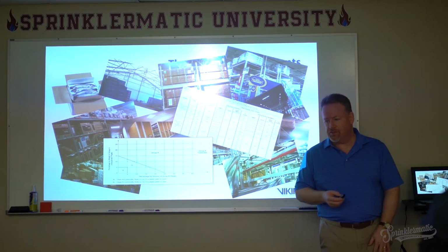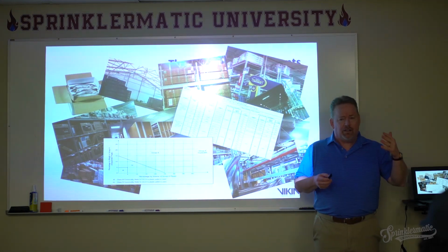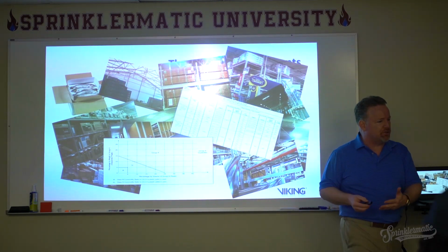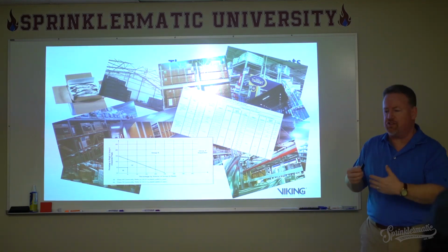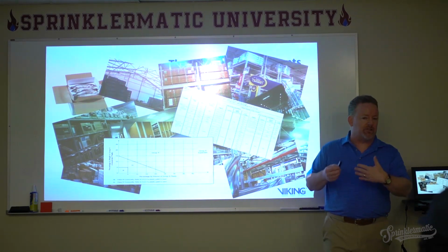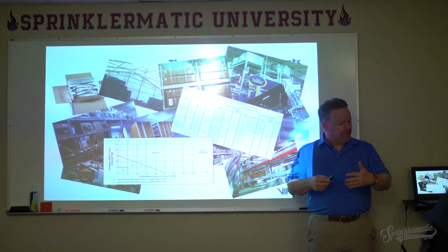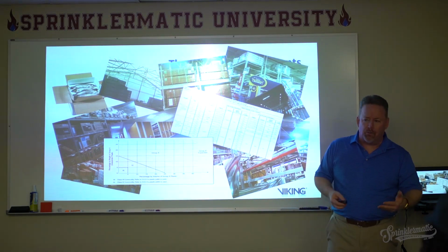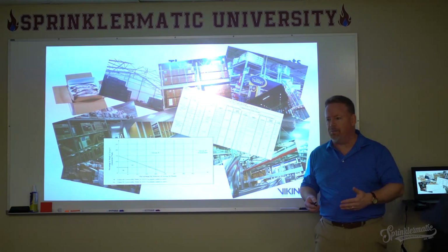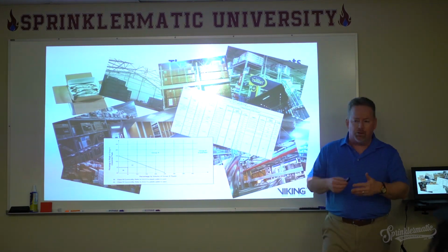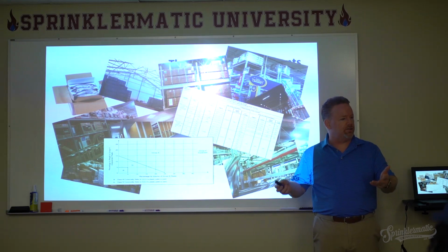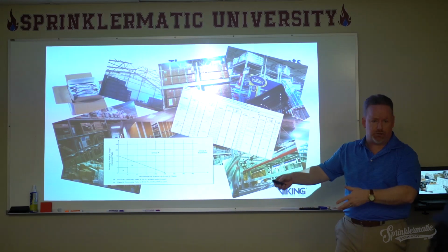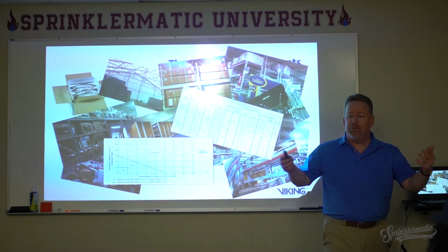Because when it comes right down to it, NFPA 13, as far as the design is concerned, has a series of different chapters that deal with the protection of storage, that deal with different ways that sprinkler systems are designed to protect storage. There's chapter 12 with the general requirements, and then chapter 13 deals with miscellaneous or low piled storage, and then we get into the piled storage or rack storage, and then special storage arrangements. And it can be very confusing.